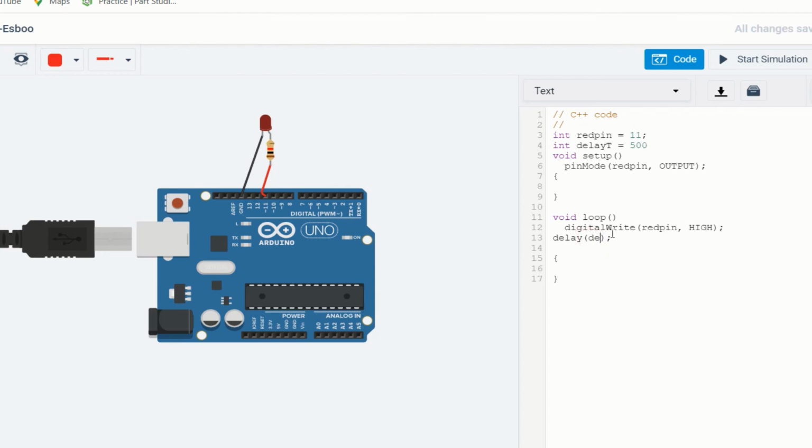That way you're specifying to Arduino that the delay time variable represents the 500 milliseconds that are needed for the wait time. You can set up an integer if you're going to do it. Instead of 500 milliseconds, you do 1,000, which is a second.